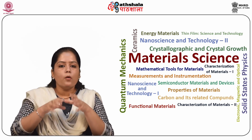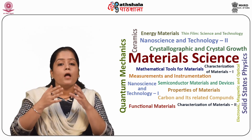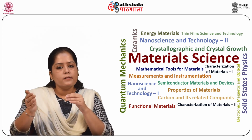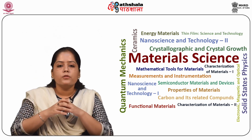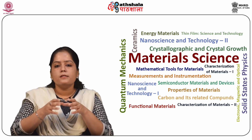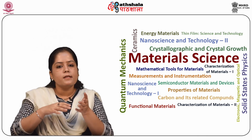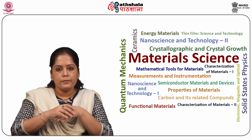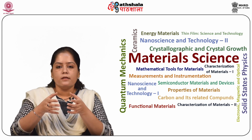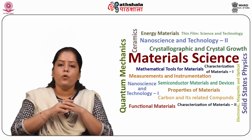Thirdly, the component acting along the direction j on a plane whose normal is along the ith axis is denoted by Sij. So there are thus 9 Sij, of which only 6 are independent. They are symmetrical and form a second rank tensor and totally define the stress at a point.